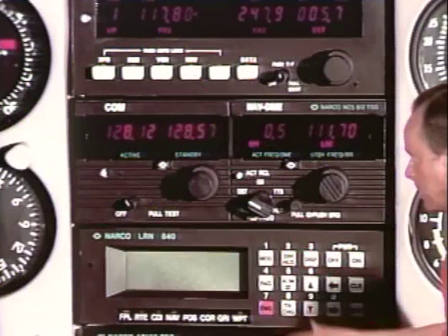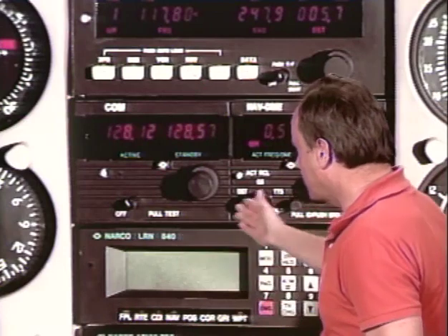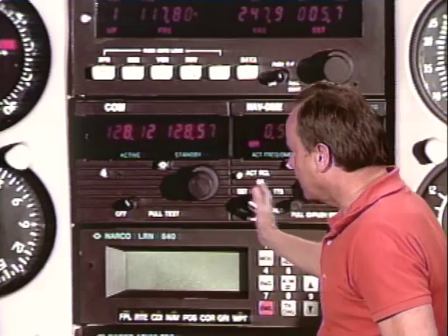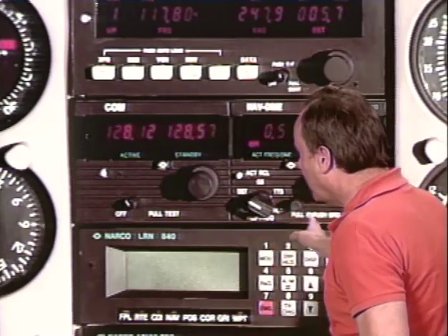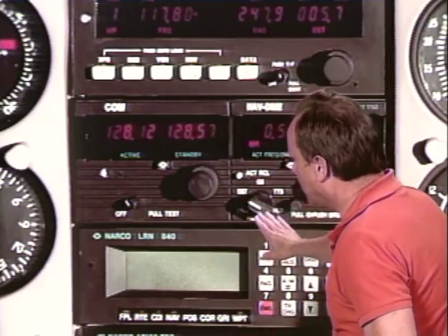Now let's assume as a mechanic you install radios or avionics in an aircraft and the antenna systems associated with those avionics, and let's assume you install them forward of the CG limit. Now the question is, is this going to affect the empty weight and the useful load of the aircraft? And the answer is yes. Anytime you install some new equipment in an aircraft, including avionics and antennas, it does affect the empty weight and useful load of the aircraft, and you would have to recompute the weight and balance of the aircraft.